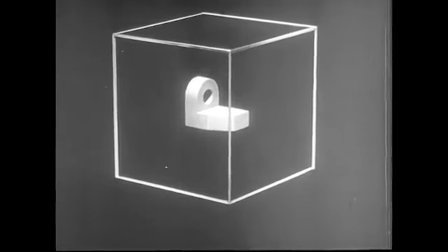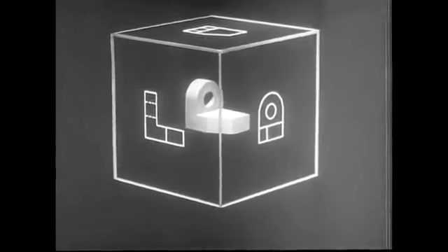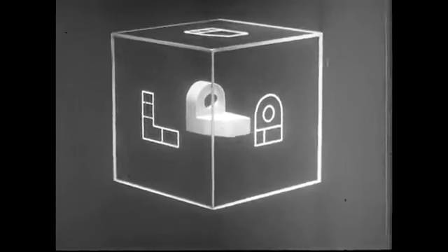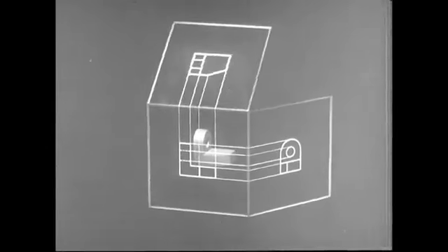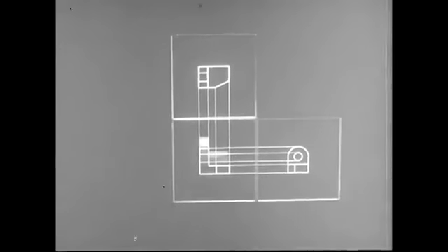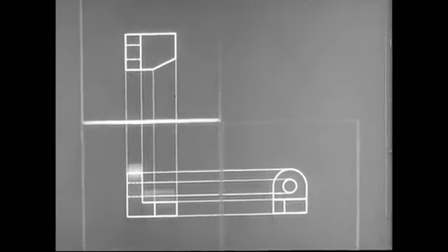You have been able to make this drawing because you know that you need orthographic views, in this case front, top, and right side views, and that each view must be an exact picture of the object as you see it from that direction. You know also that the projection planes are mutually perpendicular, and that images of the projection lines will become parallel lines connecting the three views when the planes are opened. You know that you must construct your drawing so that the views have this relationship. Then you can project points or dimensions from one view to another, and when a dimension appears in two views, you can transfer it from one to the other.